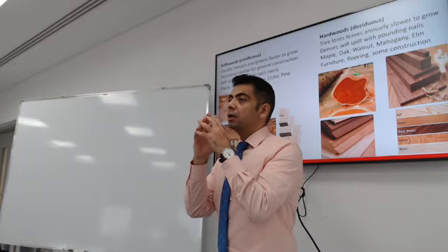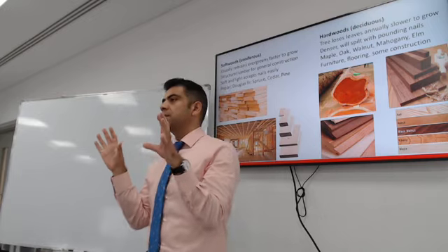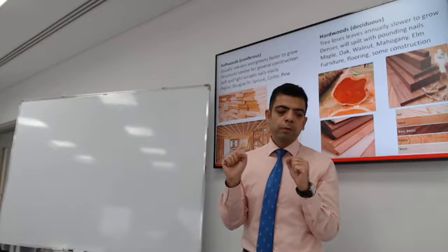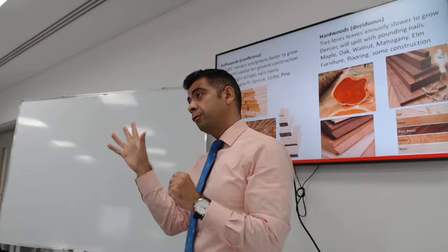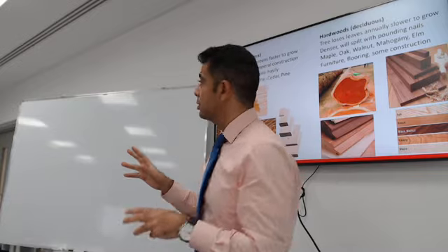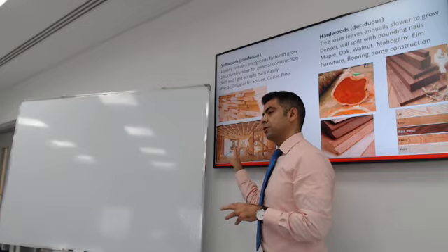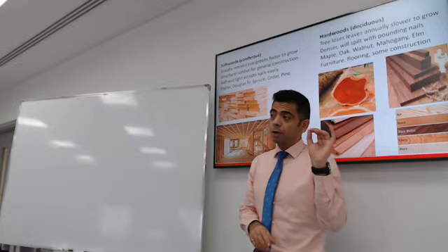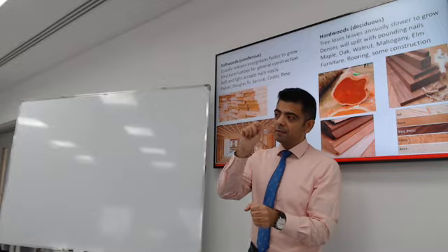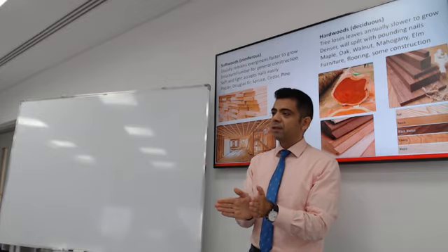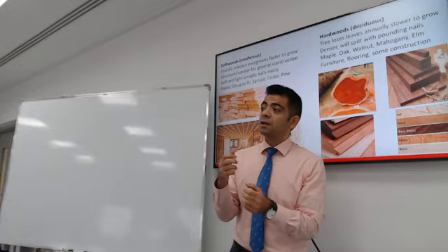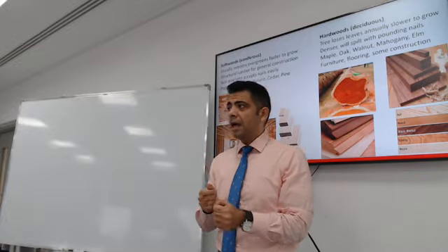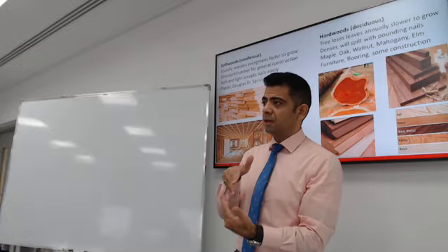You can use 2 main categories to describe the wood products, either softwood or hardwood. Softwood is mostly for construction. Hardwood is much stronger, but if you drive a nail through it, it will split easily. So it's harder to work with and does not take connections easily.